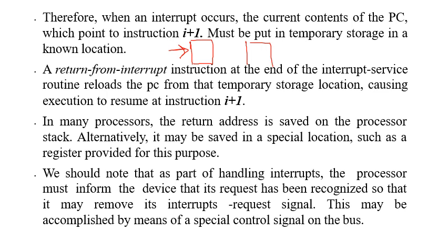At that moment, it has to execute the separate task that is written separately, that corresponds to extinguishing the fire. It may be by setting up the alarms, turning on extinguisher sprays or water pumps, or informing the agencies, whatever it may be. The instructions related to that are written separately, and that is called the interrupt service routine. In this interrupt service routine, these are written separately from the main program.